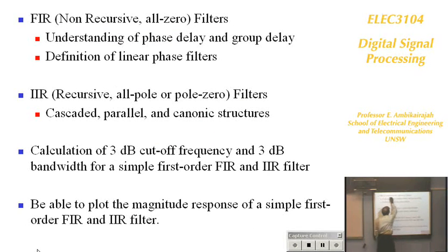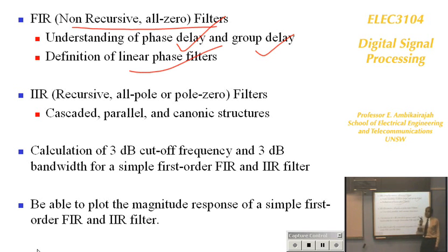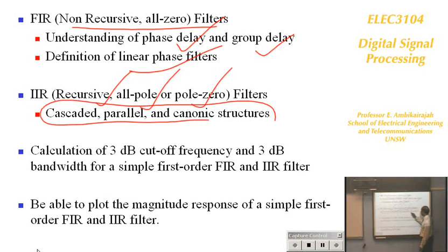You look at non-recursive filters and understanding phase delay, group delay, and the definition of linear phase filters and when to use a linear phase filter. You don't need to design them. Design will come up later on, but you need to know. Then you look at the recursive filters, which are all-pole and pole-zero filters, and then you look at the cascade, parallel, and canonic structures, and why you need canonic structures.